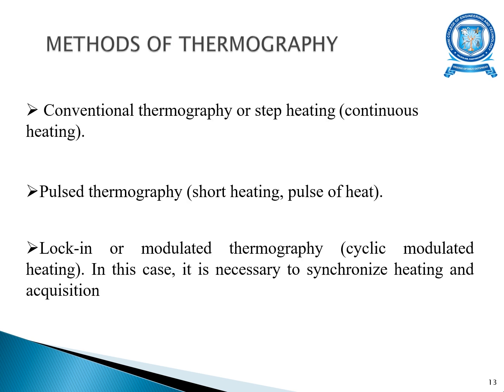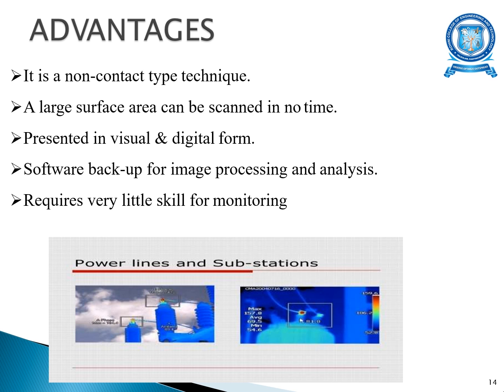So methods of thermography: you have conventional thermography or step heating, pulsed thermography, and lock-in or modulated thermography. In this case, it is necessary to synchronize heating and acquisition. The advantages: it is a non-contact technique. A large surface area can be scanned in no time and is presented in visual and digital form, software backup for image processing and analysis is available, and very little skill is required for monitoring.